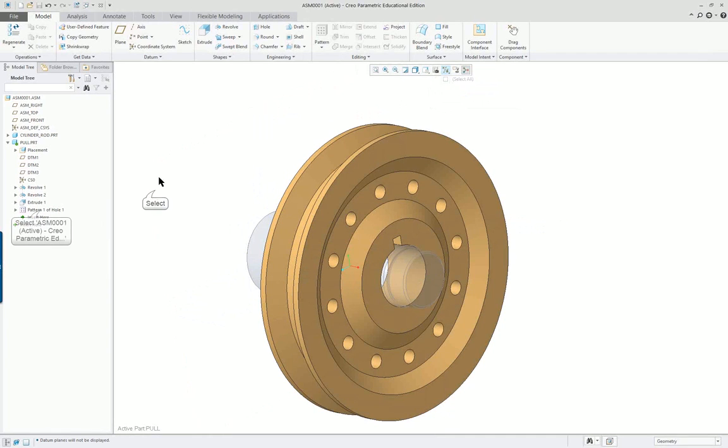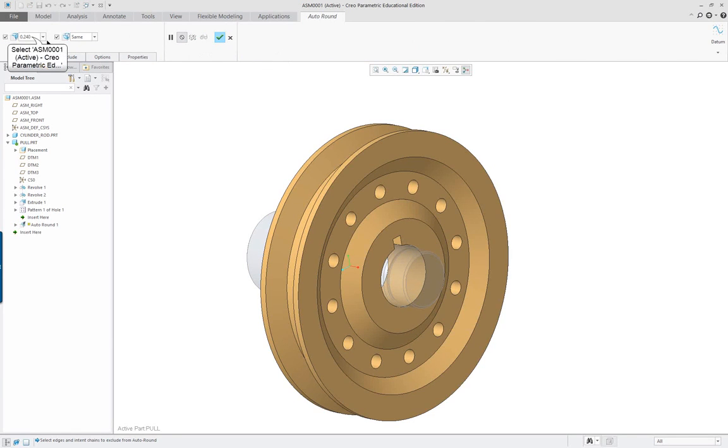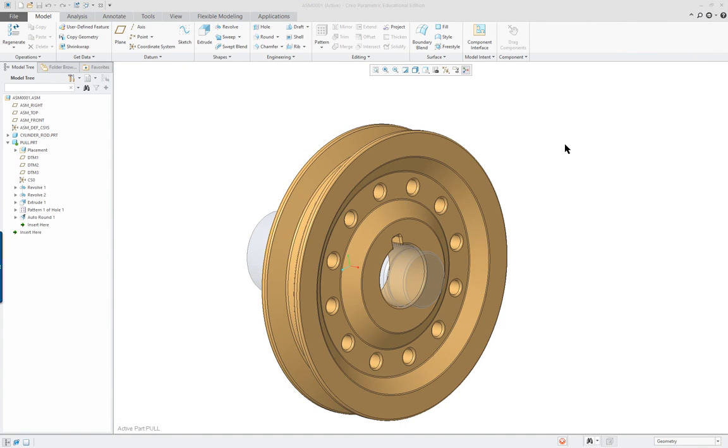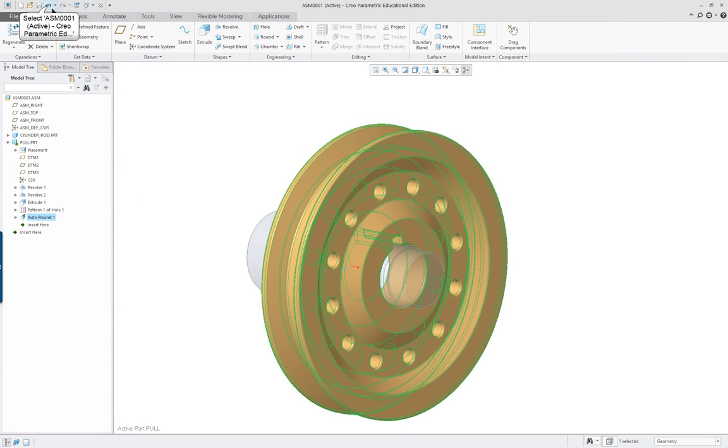Now, this is my pattern, this is my extrude. If I wanted to, let's see if I can do this time. I'm going to take this, I think I was selecting the wrong one. No, wasn't. So let's put in some rounds to finish off this portion of it. And let's make the round 0.1. Actually, I might have made it way too complicated by doing that. And it's going to slow down the process. So I'm going to undo that.